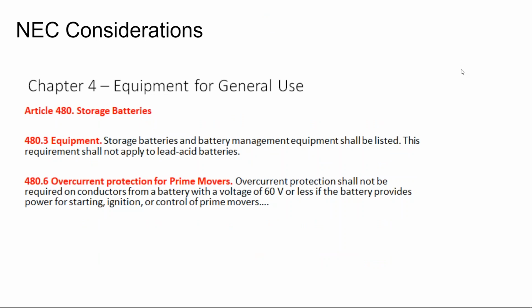Storage batteries and battery management equipment should be listed. That's not applicable to lead acid. What this really means is you can't professionally have a business where you're taking recycled lithium-ion batteries from, say, wrecked Nissan Leafs and putting them into homes, because they're not listed for that purpose.